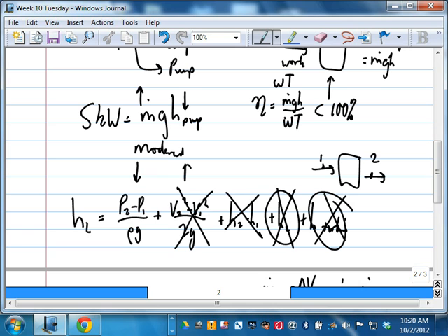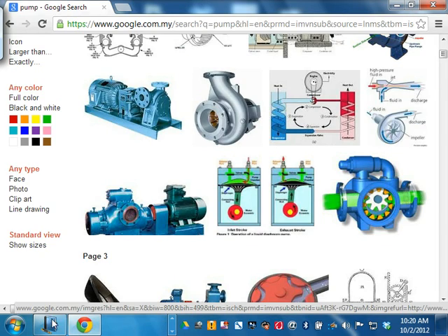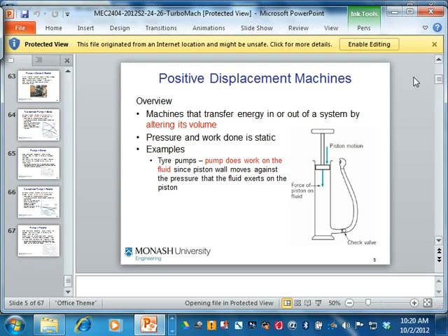Okay. All right. So we'll look at the different. When it comes to pump selection, you need to decide which situation you are in, what you want to do, whether it's a high flow rate situation or a high head situation, and choose the pump accordingly. So let's look at the different types of pump. Okay. All right. I'll come back there. I see some nice pumps there.